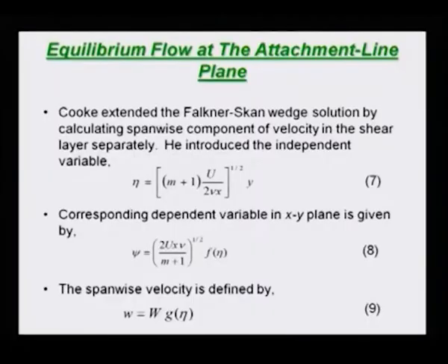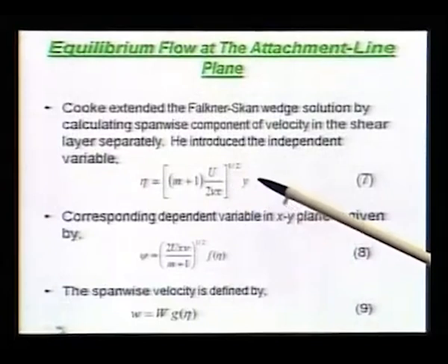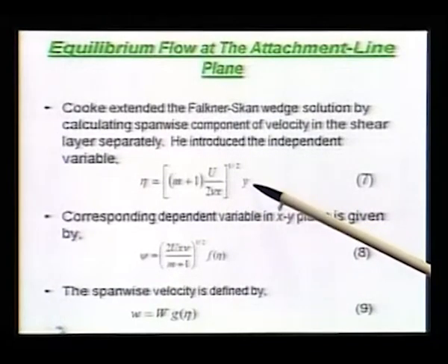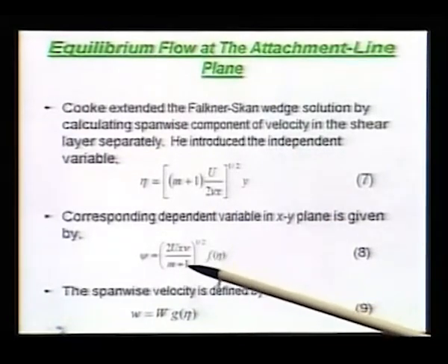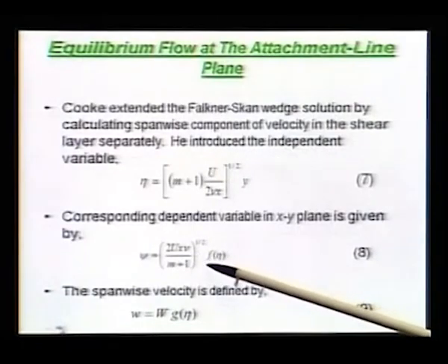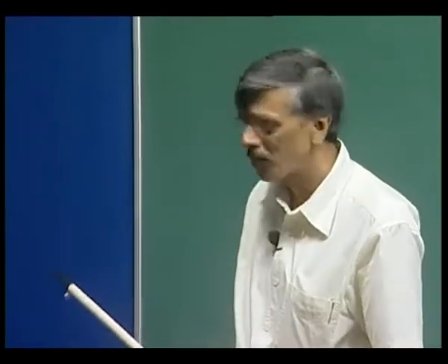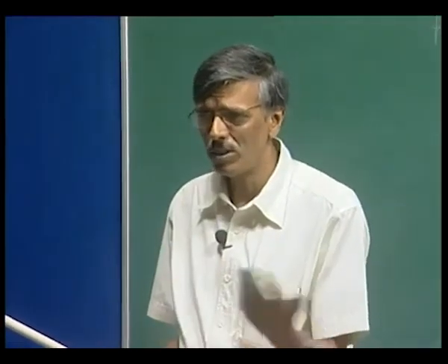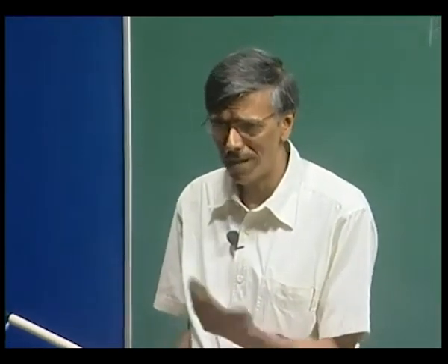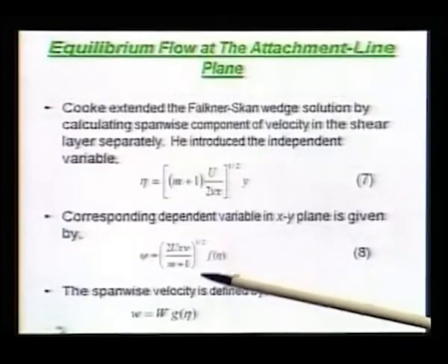So, that is what comes here, and you scale it by Re by square root of x, and it is the y coordinate that is stretched. So, you are stretching that way. You also define a stream function. What is the idea here? Of course, when you introduce a stream function, then in the xy plane you do not need to worry about mass conservation, it is automatically satisfied. Existence of psi will give you that.